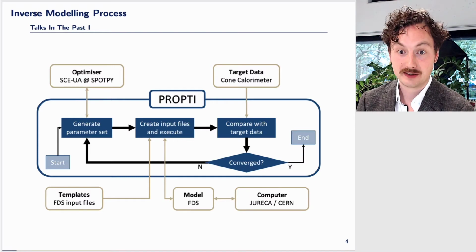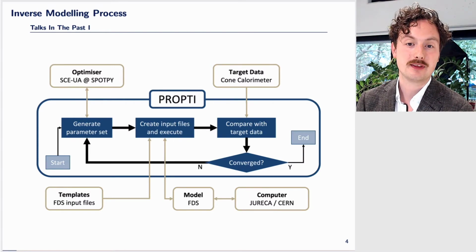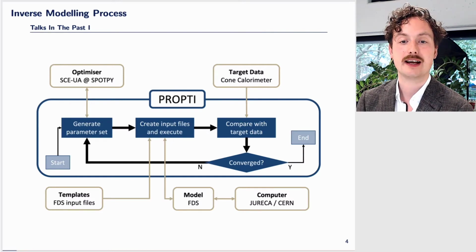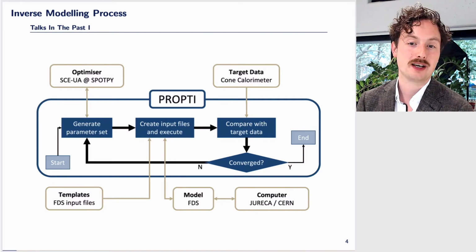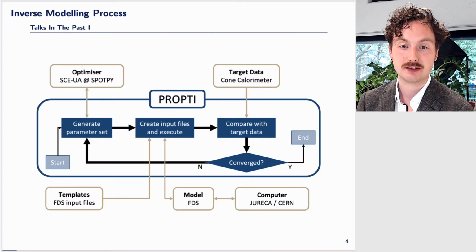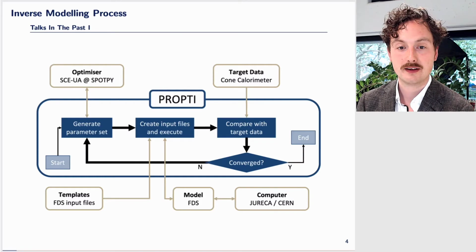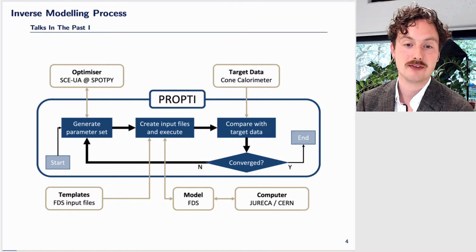One evaluation step looks like this. The optimizer is called to define a set of current parameter values to be evaluated. Models are executed, the simulation data is extracted, and then passed to the optimizer. The optimizer compares the experimental and simulation data and generates a fitness value. This is the cost function. The optimizer decides if further evaluation steps are needed based on the fitness value.